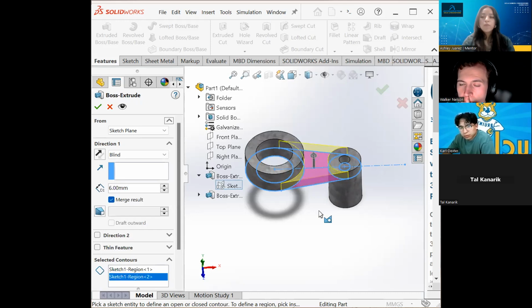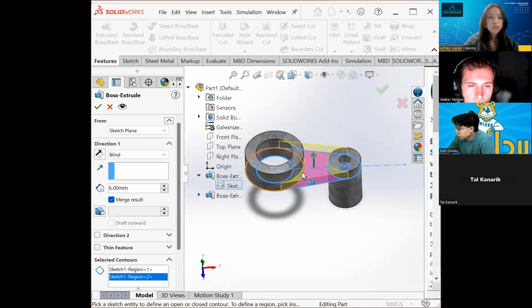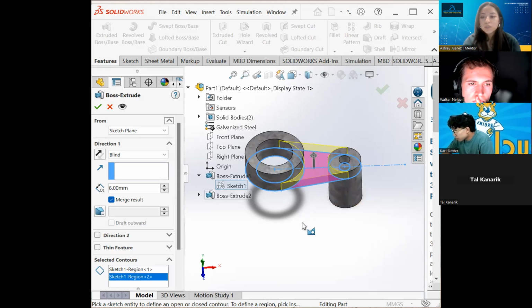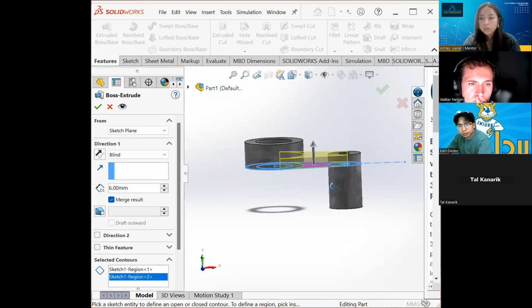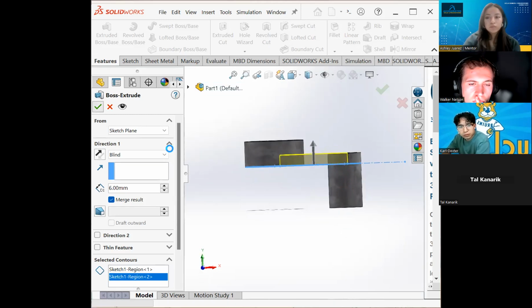Does that make sense? If these circles, right, like from this perimeter, if I would have cut out a specific area, it would have counted it out as like an entire piece. But that's the reason why I used solid lines. I just didn't have anything intersecting on it because I wanted it to register that it's one solid piece. I'm extruding this entire piece. I'm noticing that this little plank here is also 6 millimeters. And I know that because it's not varying in height with my other platform that I did previously, right? So I'm going to select 6 millimeters, which is already so wonderfully selected for me. And I'm going to press OK.